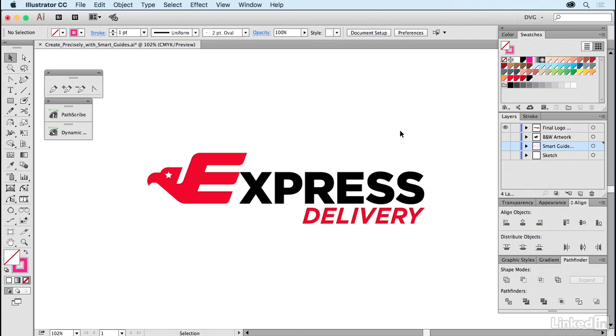You're going to use this a lot if you're doing shape building techniques. When it comes to other features like organic freeform shapes, it's also going to assist you in that respect as well, but you'll have to toggle them on and off. Once again, it's Command U, and you'll want to toggle them on and off as you build, because sometimes it'll force the anchor point to snap to something. You don't always want that. So if you know what that keyboard command is, you can easily just toggle it off when you don't need it, and then when you need it, toggle it back on.